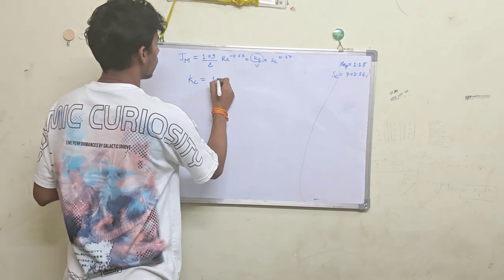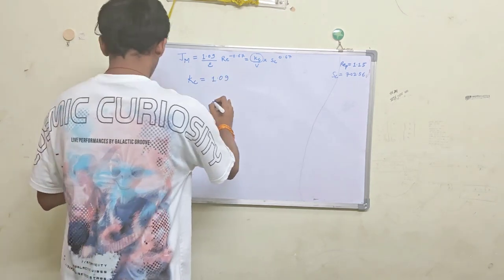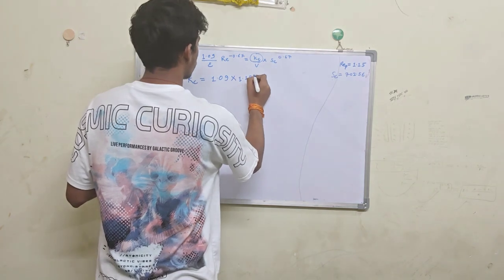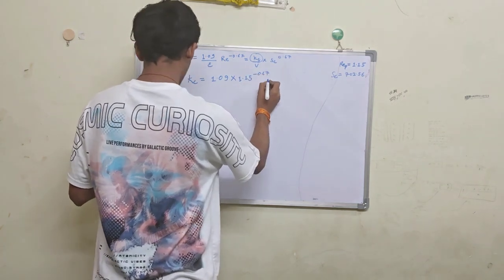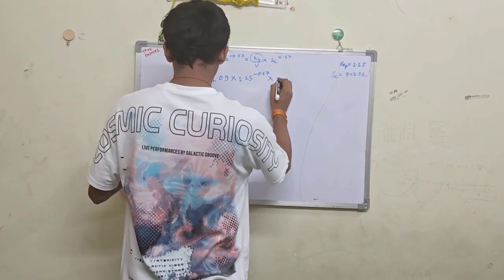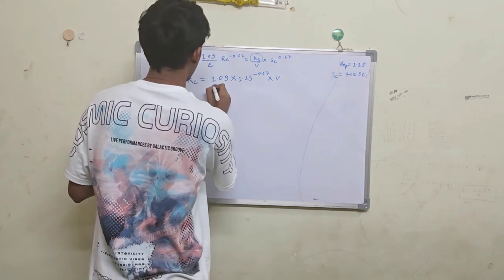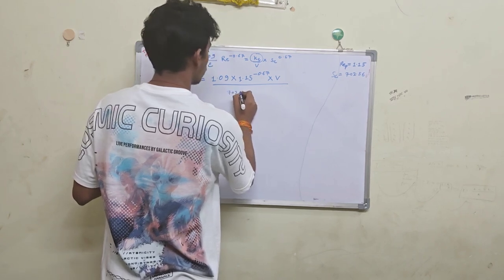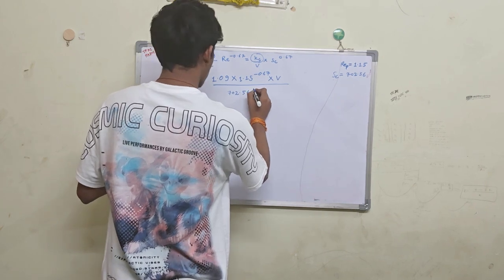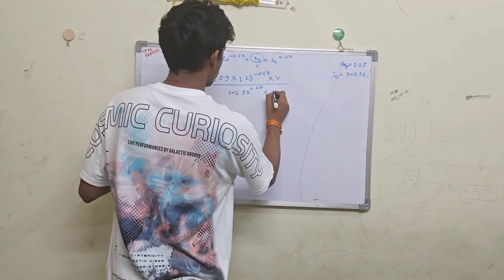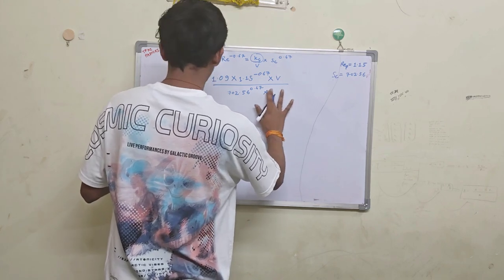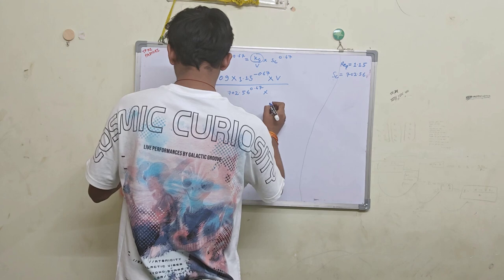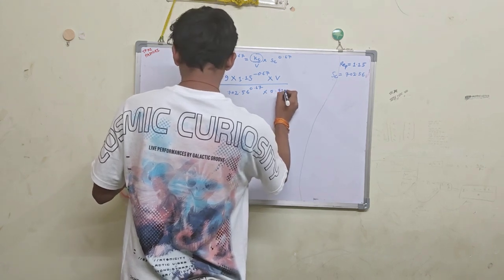Kc is equal to 1.09 into Reynolds number value, 1.15 to the power minus 0.67, into this velocity which we have calculated, divided by Schmidt number 702.56 to the power 0.67. Epsilon was given as, what was the epsilon value? 0.436.